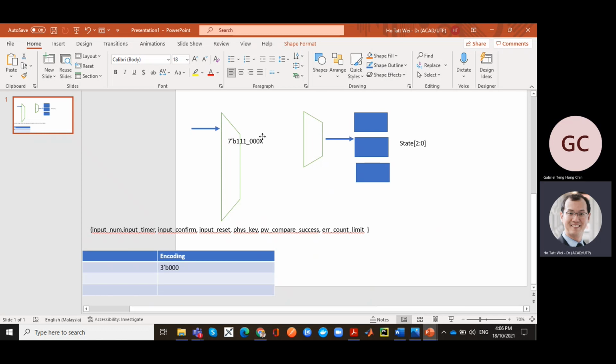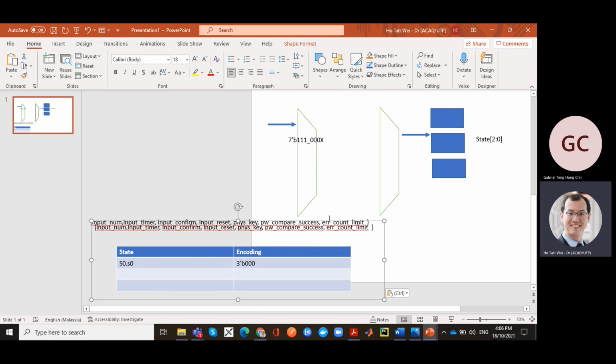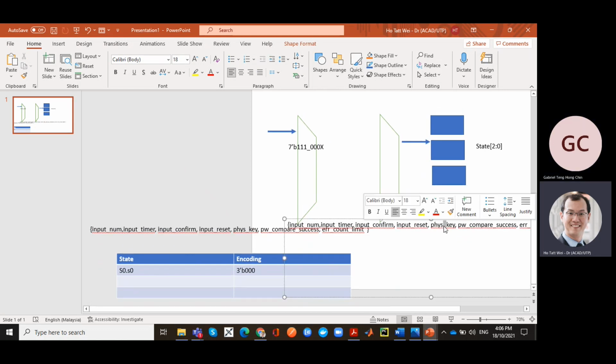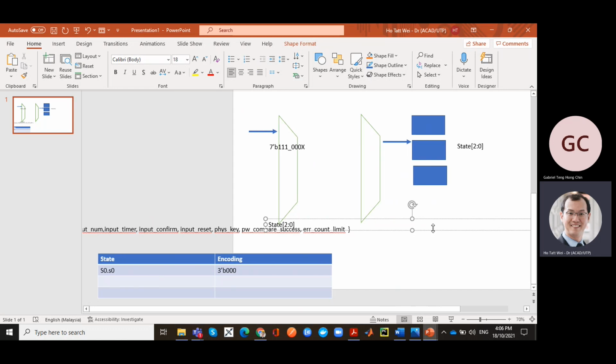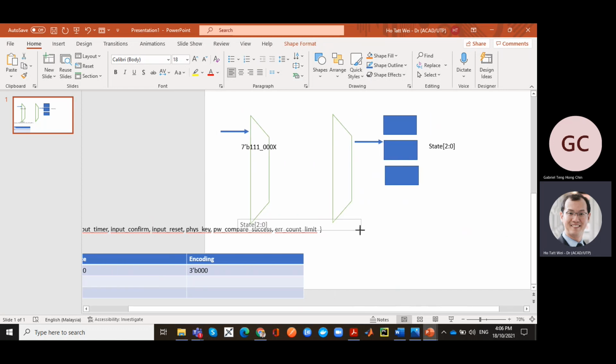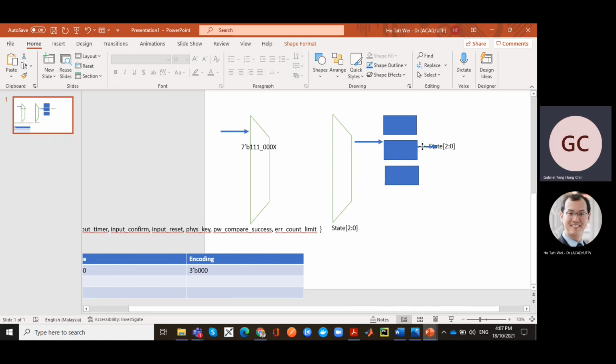That's for me, because then I can just say if I'm in state 1, then I know in state 1 what the input-output transitions are. I directly encode for that. So here I will put your current state, because it's dependent on your state. The transition is dependent on two things, which are the inputs as well as the current state. The current state is nothing else but the output of here. Okay, can or not? Yeah, I will follow you first, and then you ask the questions.